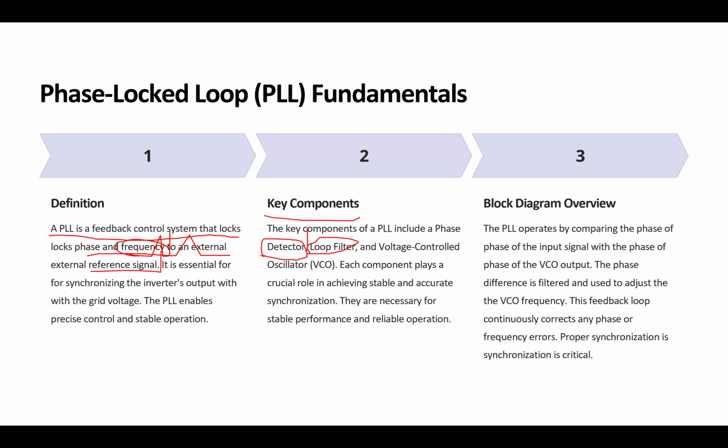Okay. And when we did that, we detect the frequency, we filter out the variation and noises from that estimation. Then we will have a voltage controlled oscillator, normally like a BJT oscillator in practice, that uses the frequency output of the filter to create a sinusoidal with the same frequency.